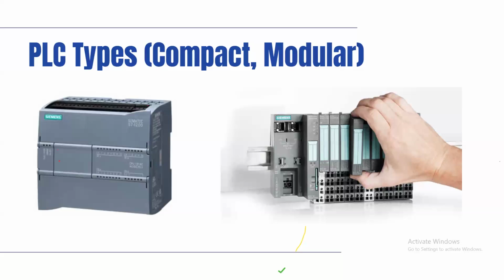You can say, okay, I need 10 digital inputs, 4 digital outputs, 2 analog inputs, and then I'm good to go. This is the PLC that will suit my needs. So you typically find it with OEM supplied machines. If an OEM supplies you maybe a small mixing machine or a small cutting machine, they know the number of IOs that are in that machine. They don't expect you to modify it. They will just put the PLC that they think is appropriate because it's cheaper, and they call it a day.